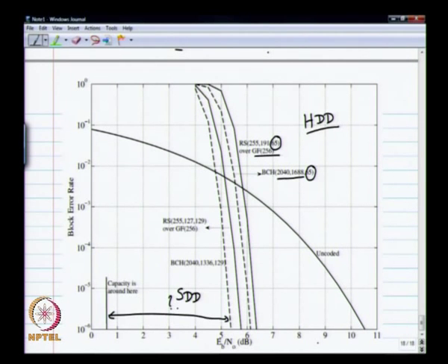There are some soft decoders for Reed-Solomon codes which give you about 2 dB or so additional coding gain, maybe maximum 2 dB, but nobody has shown that it can get to 1 dB or something. There is no such result that for Reed-Solomon codes you can run some decoder, even ultra theoretical. Let's say some decoder is very complex, but somebody has analyzed it and shown that it can. Of course, if it's so complex, you can't simulate, right? You have to analyze. Nobody has done that. But for other codes, people have shown even simulation results very close to capacity.